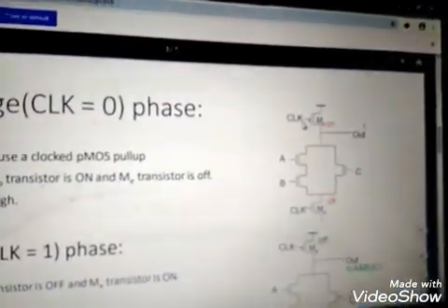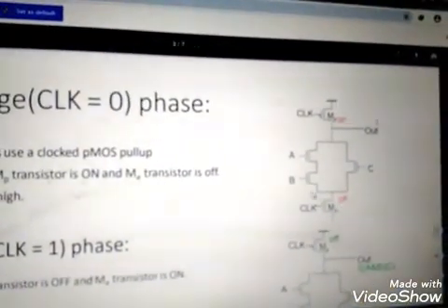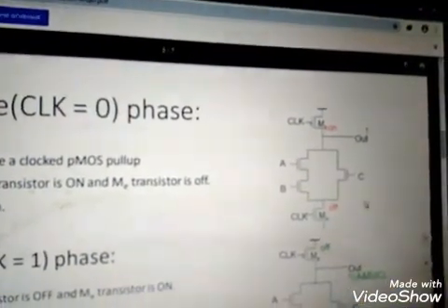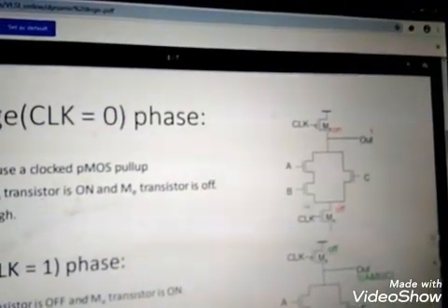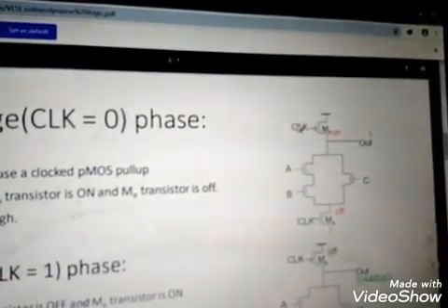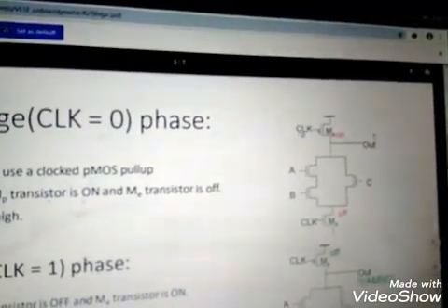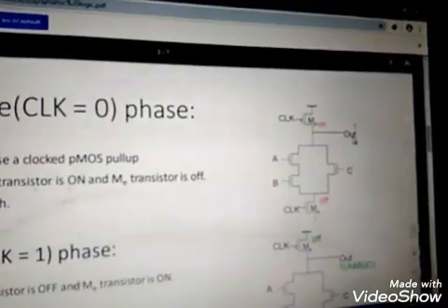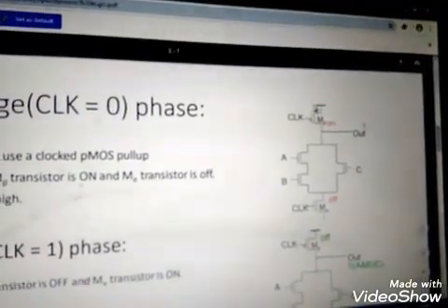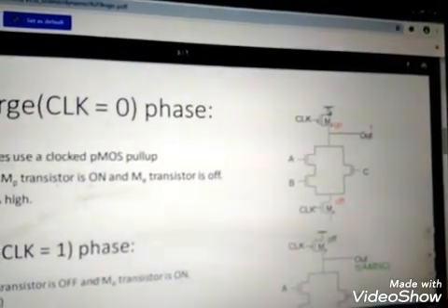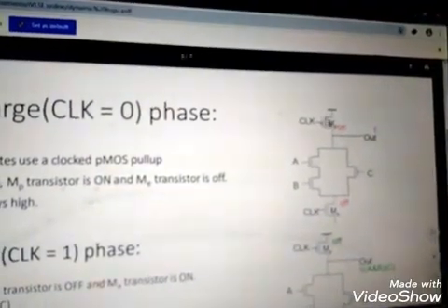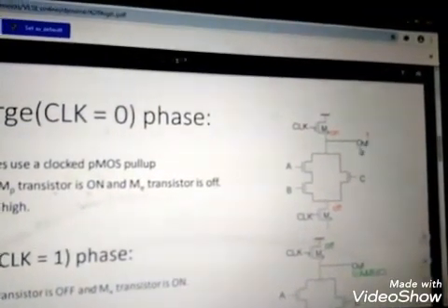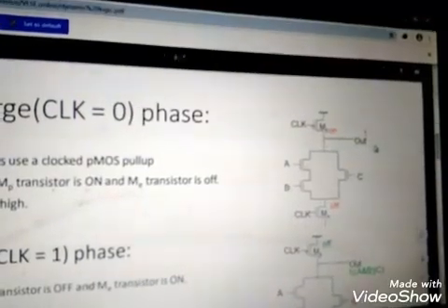Just we'll go into the circuit. So look into the circuit where pull down network is going to be with NMOS transistor. It's a logic implementation. But when you go with the pre-charge phase, clock is equal to 0. So this particular node, the output node is charged to VDD. So this is pre-charge. Why we call it as pre-charge means output node is charged to that value.